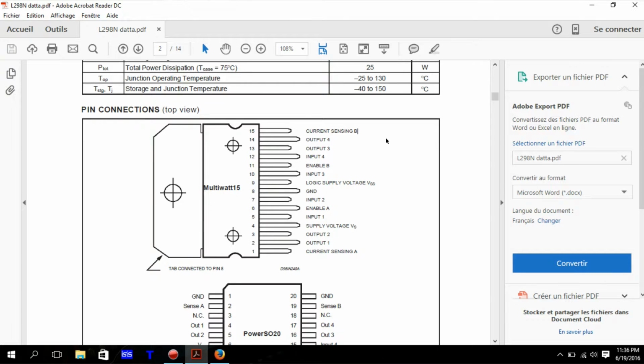Okay, for this reason, in case you wanted to measure the current that your motor is drawing, so you have a big system and it shouldn't draw more than 2 amps for the sake of your motor or your device, or even for the sake of the motor driver, because if it's drawing more than 2 amps, it will go super hot, which actually for this specific chip you need a radiator, a heat sink, which goes here.